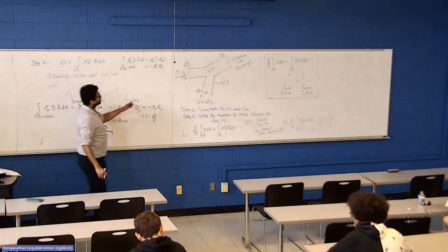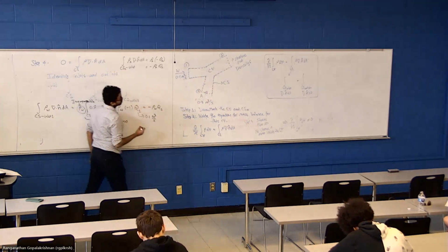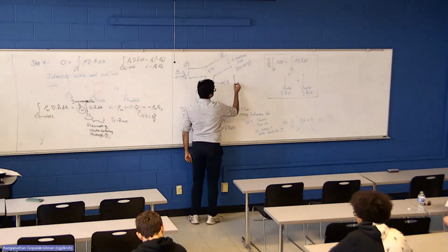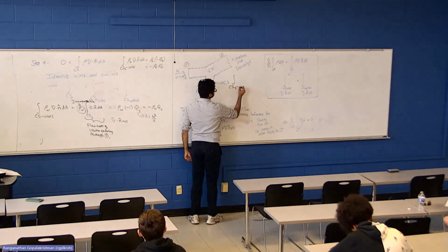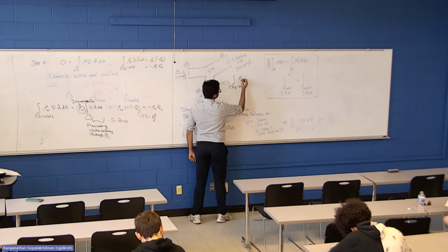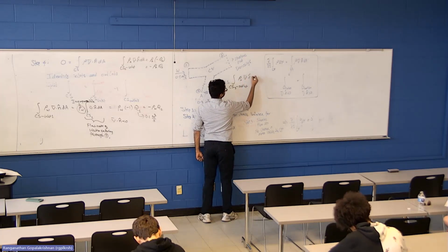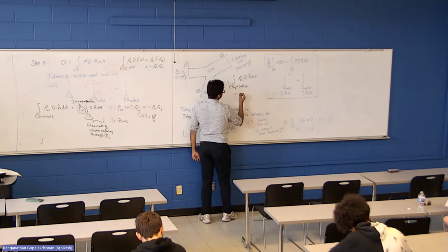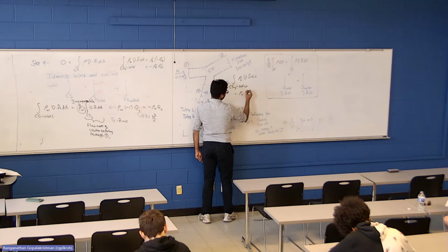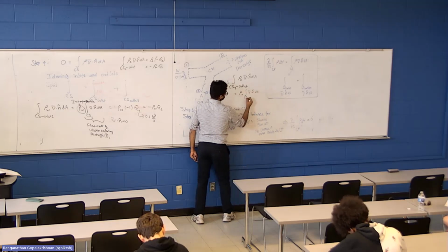And what about section 3? Integral over CS3, which is an outlet, of rho unknown, which is what we are trying to solve for, times V dot N dA. So that is like writing integral rho u times integral V dot N dA over CS3.